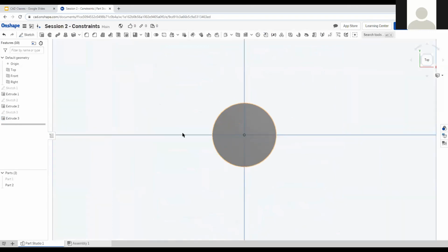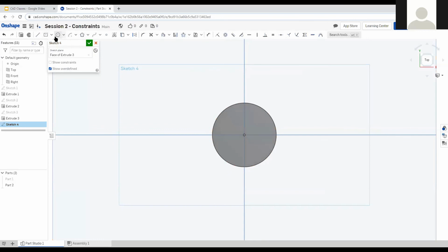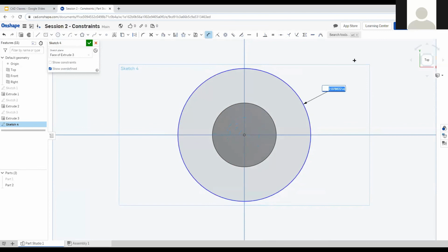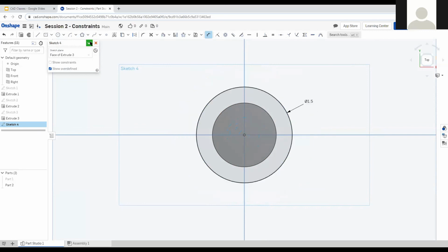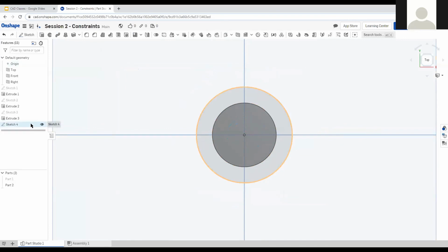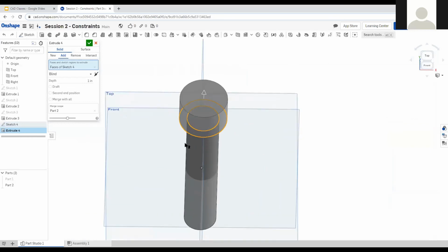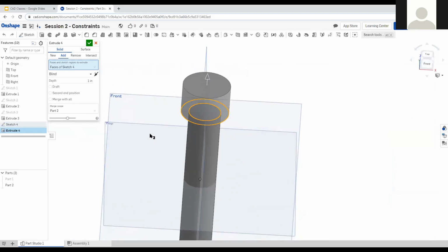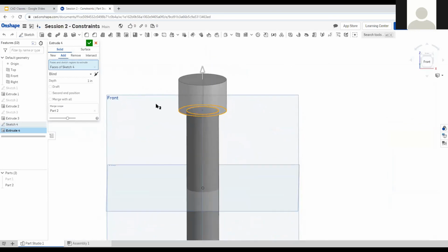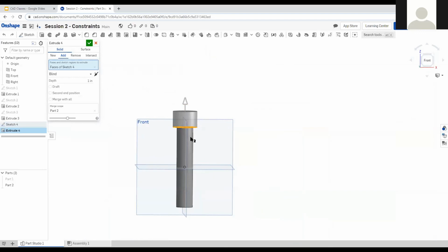Since I'm trying to make the robot model look better, I want to put a thing on the top to represent the bolt's head. Let's just make this a pretty big one. Let's go with 1.5 inches. That looks about right. Forgot to actually extrude it. Yeah, so now since we're just trying to add a bit on the top, this is a really nice way to add anything on the top. Alternatively, we could create that area as a sketch and just revolve it. But that's something we'll be going on to next lesson, I think.